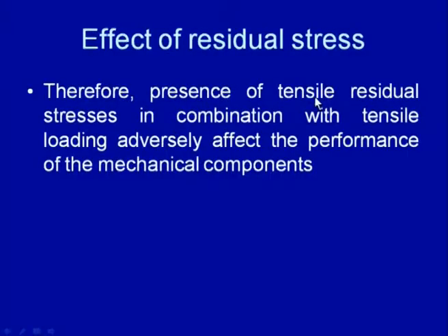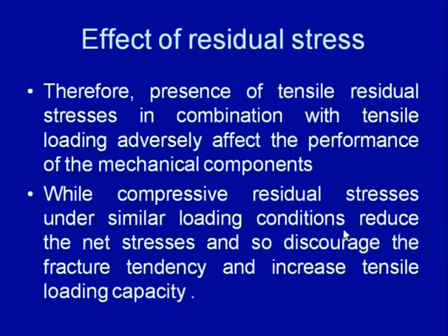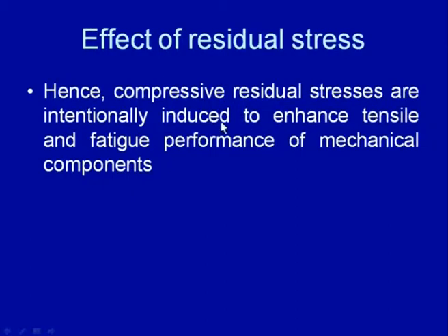Therefore, the presence of tensile residual stresses in combination with tensile external loading adversely affects the performance of the mechanical component, while the compressive residual stresses under similar loading conditions reduce the net stress, so discourage the fracture tendency and increase the tensile load carrying capacity. So, for enhancing the tensile load carrying capacity, it is favorable to have compressive residual stresses in the weld joint, so that the net stresses acting in the component or in the weld joint can be reduced. Hence, the compressive residual stresses are intentionally induced to enhance the tensile and the fatigue performance of the mechanical component,